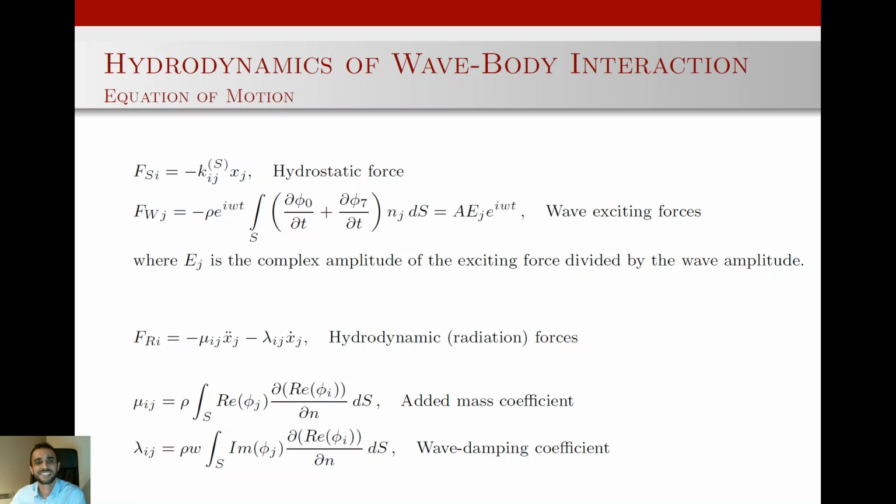So now let's summarize all the forces that we have and look at them one more time. We have the hydrostatic forces, which are related to the buoyancy effect and hydrostatic forces on the object. We have the wave exciting forces, which are due to the incoming and diffraction potentials, an integral over the surface of this.